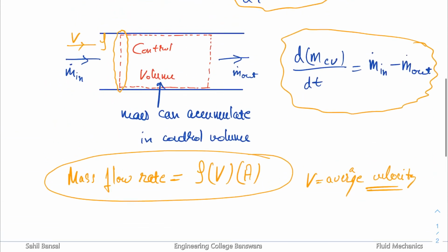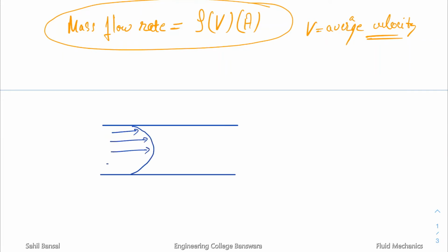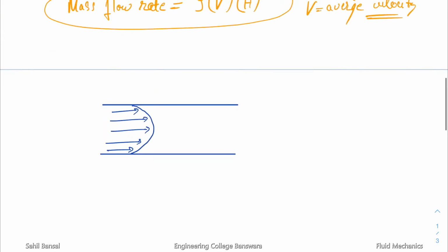As you know from Newton's law of viscosity, which we have discussed earlier, if this is my pipe, my velocity profile will not actually be the same. It will somewhat be like this. We have discussed it already in the class, right? The velocity near the boundary will be less and it will be the maximum at the center. In pipe flow, we can derive this by Newton's law of viscosity. Let's leave it till now.